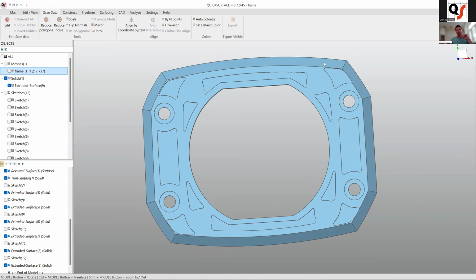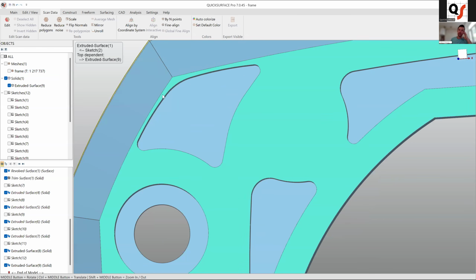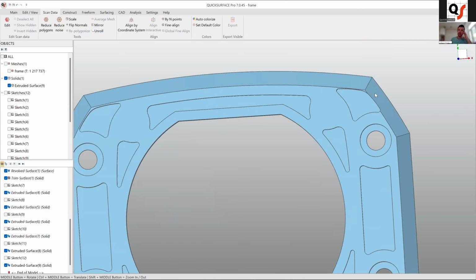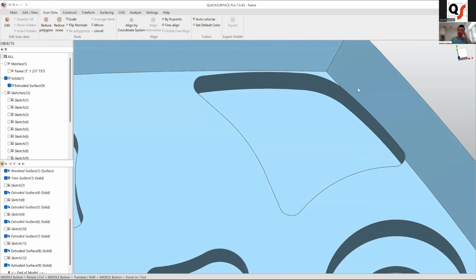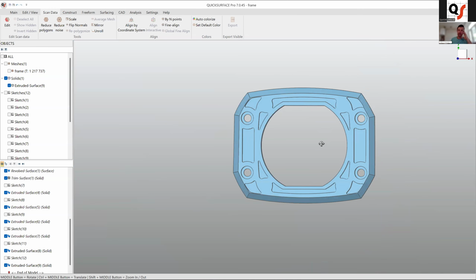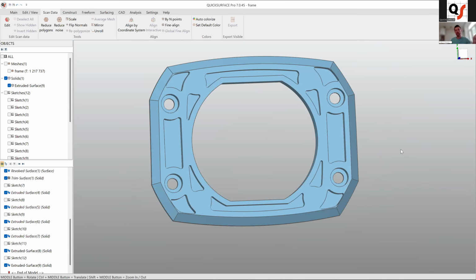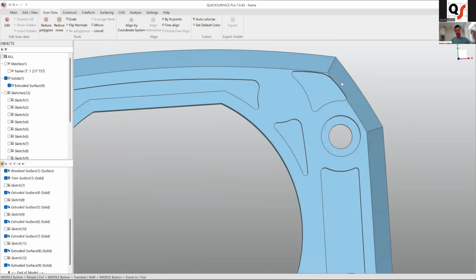As a beginning, I just used the outline of the scan data of the imperfect cut part. And here you can see in the result, as all features were mirrored, on this side we have a nice little edge around it. For example, here it's already climbing onto the chamfer. So basically, I started with the non-perfect profile of this part, extruded it, and then I started to build these cutouts like in the perfect cut model. And this way I got to this error right here.